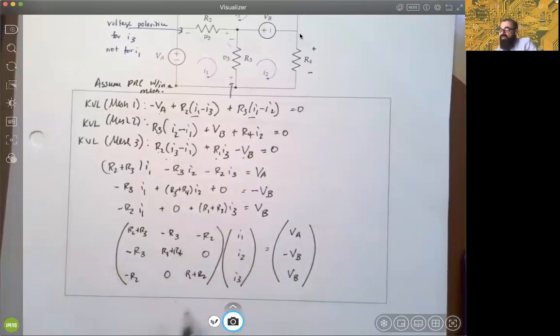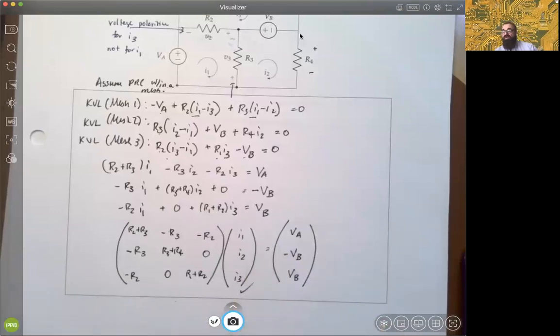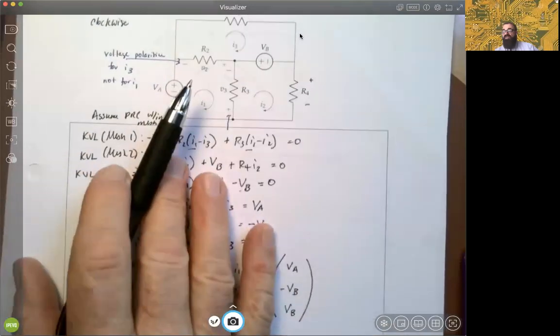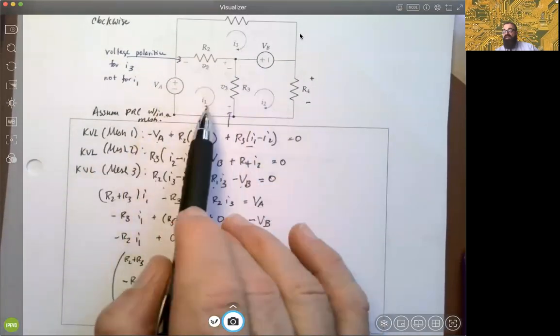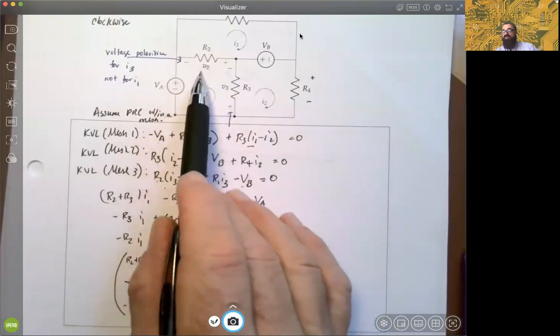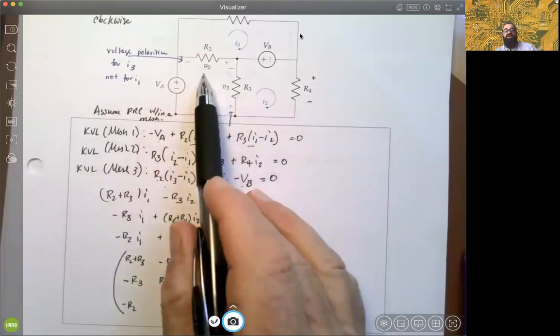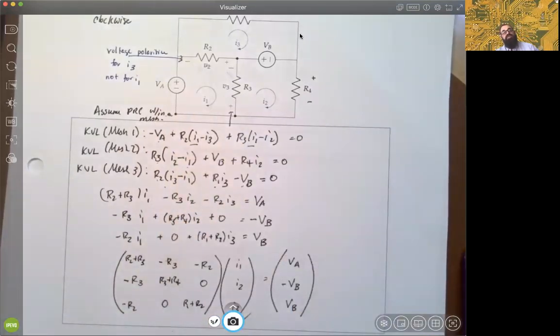So you would have all these resistances, you would have the values of the voltages of the voltage sources, those would have to be given to you. Plug that into your matrix solver and out comes the mesh currents. And if you have the mesh currents, we know what the voltages are at every one of the resistances, okay?